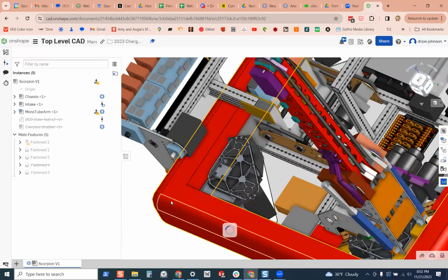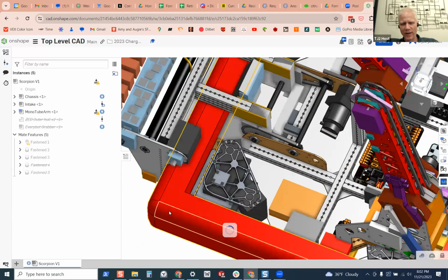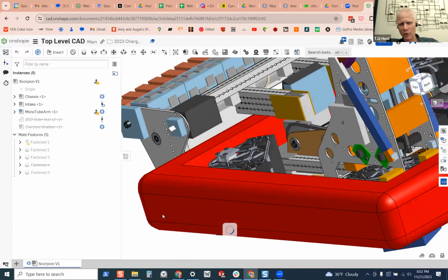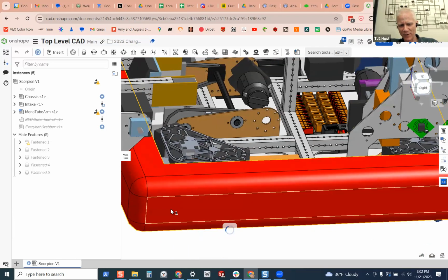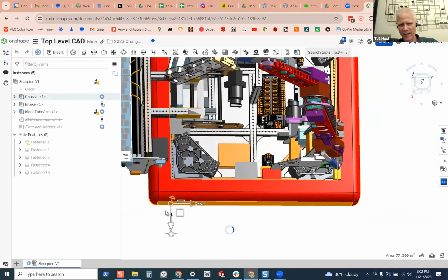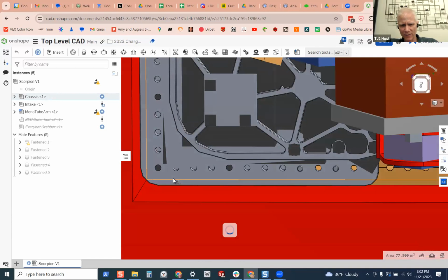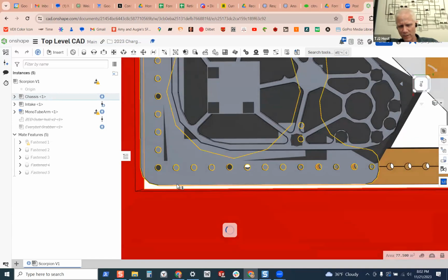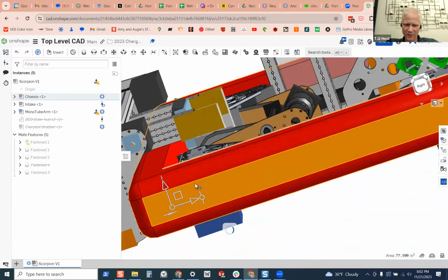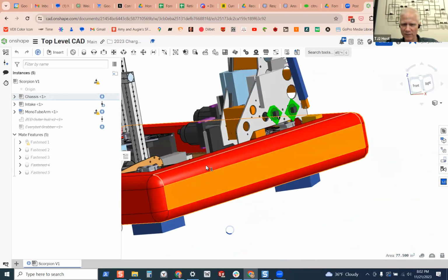So it goes around the whole robot just like this. You're trying to make this piece right here. It needs to have a gap of 1/8 of an inch between the bumper and the chassis, and it needs to be 5 inches tall. Onshape is thinking like mad here because this is a big file.